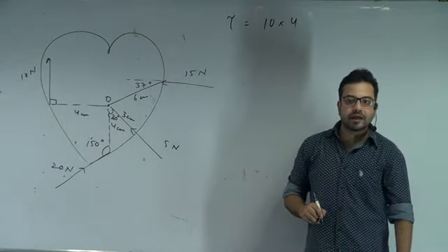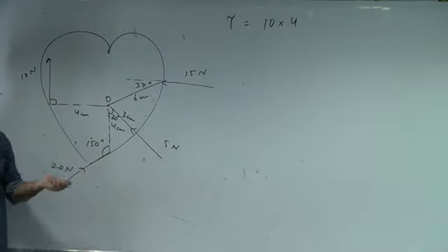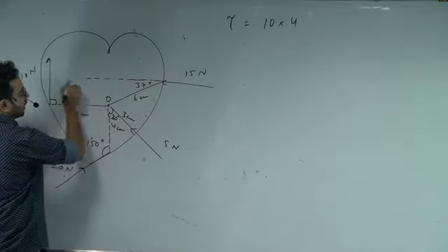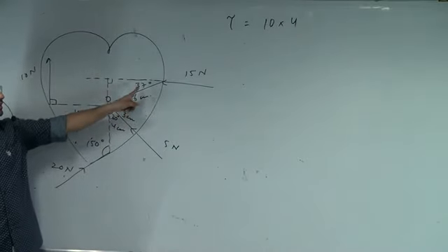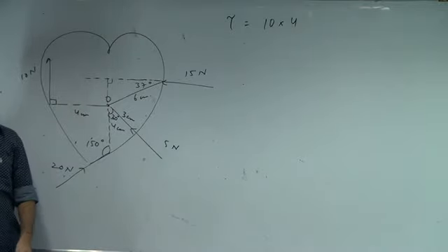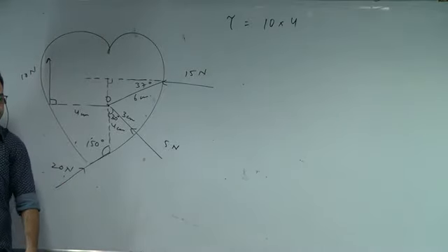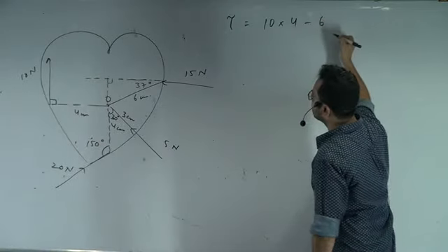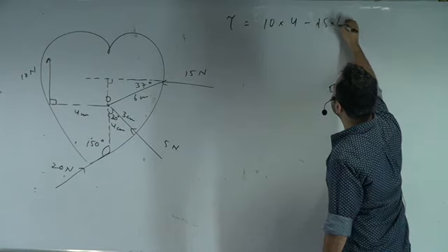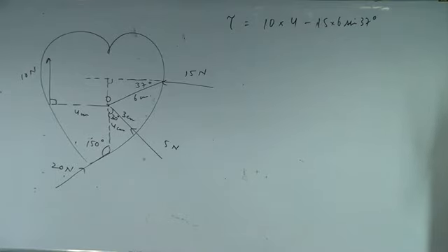First of all, the torque is anti-clockwise. Now extend the line of action of force, and then drop a perpendicular. So this is 6, this is 37 degree. What will this distance be? 6 sine 37 degree. So the force is 15 and this is 6 sine 37 degree. My job is done, and it is anti-clockwise, so I am going to write minus 15 into 6 sine 37 degree. Is that clear? Any problem? We will calculate it at the end, remember that.